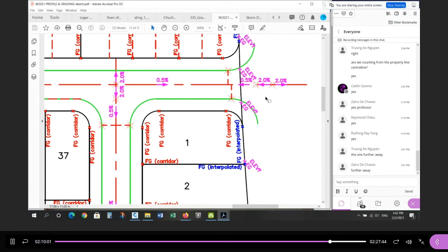Okay, so what you need to do, and if you remember the procedure from last semester, is put points, AutoCAD points, on the plan so that you can transfer them to the profile to establish the station location for the PVIs, not the elevations. We do that design in the profile. But we need to locate key points in plan so that we know where they are in the profile. And this should be familiar to you. Remember the intersection, the beginning and the end of the elbows, the beginning and the end of the cul-de-sac. Remember all the special points where you go from a typical right-of-way to something wider, something unusual? Okay, so that's what we're trying to identify here.